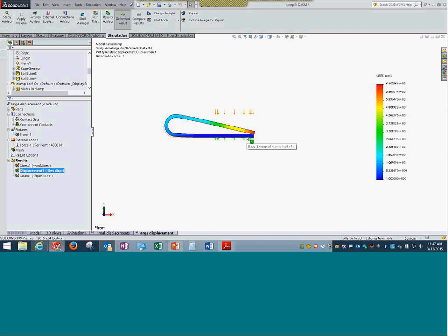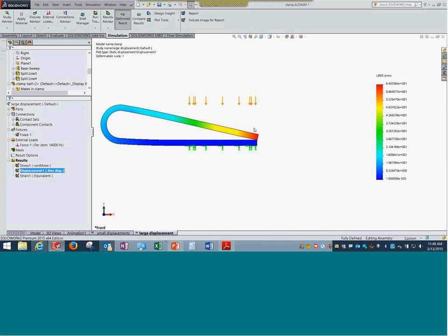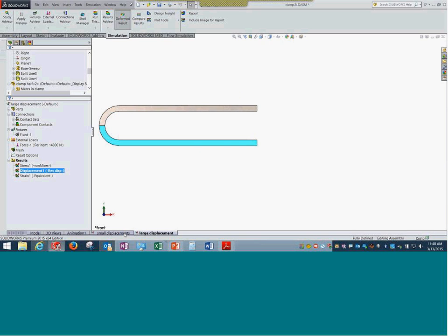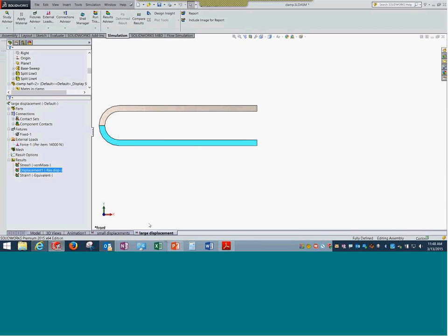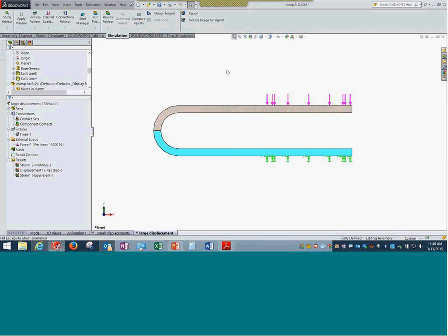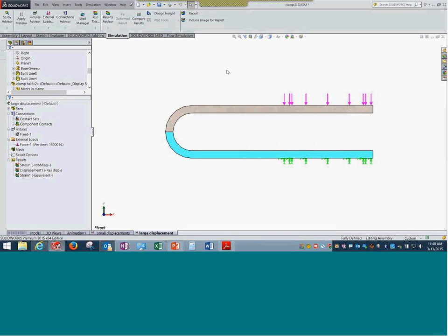The final result is more realistic than what we saw before. In this case, we are seeing some visible displacements happening, and we have activated large displacement, and this is the final result. Obviously, it is far different from what you saw here, and with large displacement, it is definitely more accurate. But as I told you, this is a non-linear thing. This is a very sensitive topic in terms of what we can and can't do here. Neither do we have too much help or explanation on this.